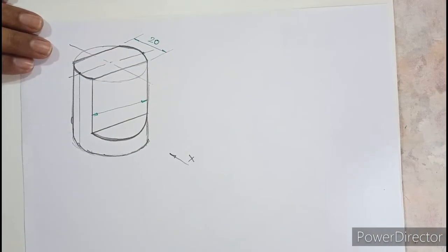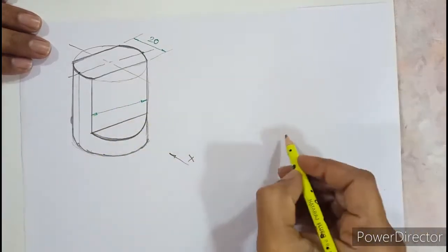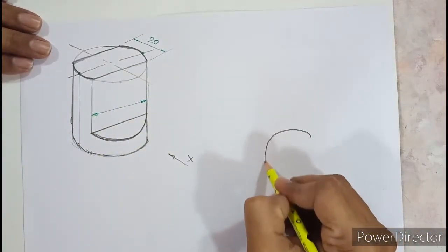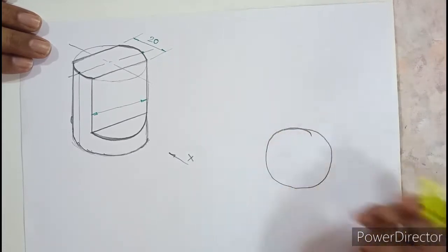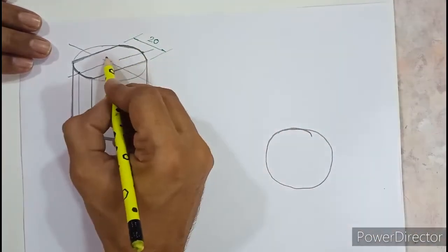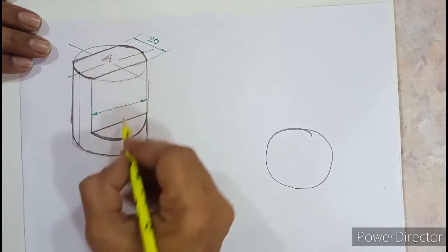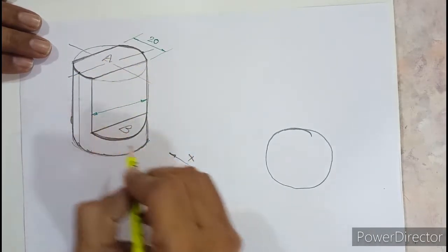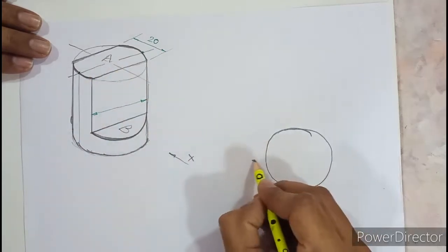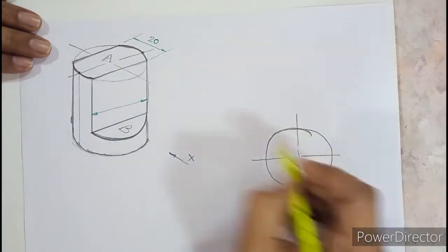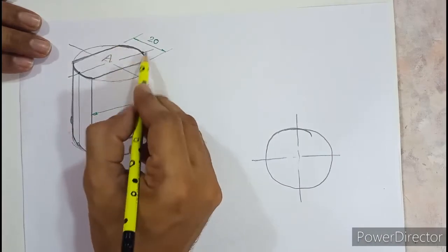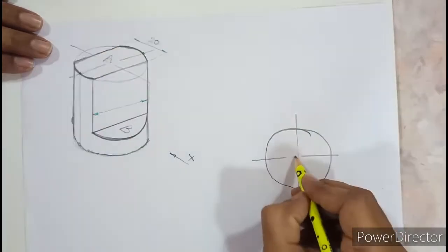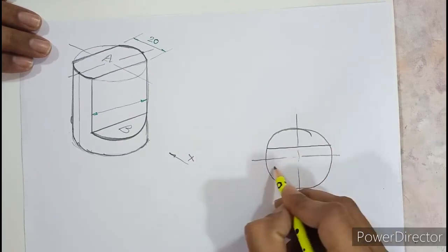And we already discussed that whenever you find a cylinder in an object, always start with the view from where the cylinder is seen as a circle. So here you can see a circle from the top view. So in the top view, I draw a circle like this, correct? But apart from the circle in the top view, you can see surface A and the bottom surface B on both the sides. Looking at the center of the circle, this dimension is 20, so from the line of symmetry it is 10 each. If I move 10 up and 10 down, you'll get two lines.